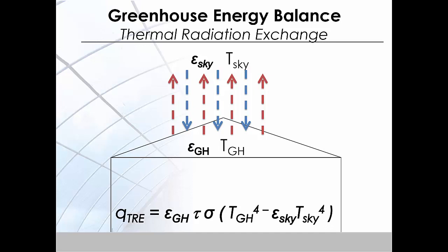When it is raining, for instance, or completely overcast with fog or low clouds, the effective sky temperature is the outside ambient temperature. The clearer the sky, the lower the effective sky temperature. When the sky is very clear, as on a crisp, clear winter night, the heat loss by radiation is maximum.